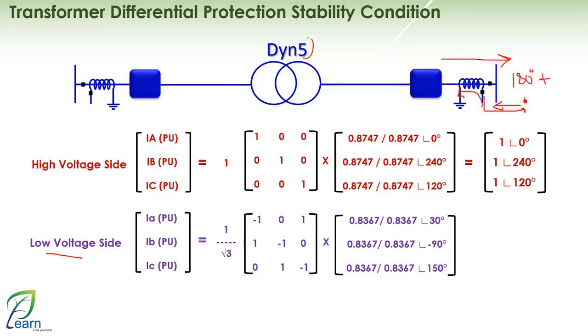So what is your value? 5 times 30 means 150 degrees. But these 150 degrees mean negative 150 degrees. So what is the sum of this 180 and negative 150 degrees? Therefore, the current that will be read on the relay screen, or that will be used and multiplied by the compensation matrix to calculate the differential quantity, is 180 minus 150, which is plus 30 degrees. Okay? And of course, for the other phases, you will subtract 120 and add 120. Quite simply, all you need to do is deduce the first phase only.